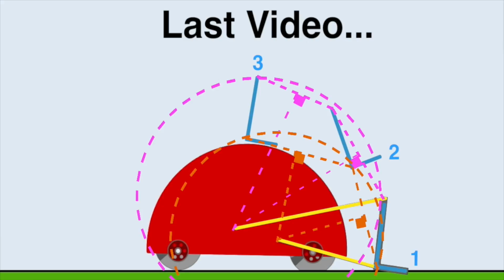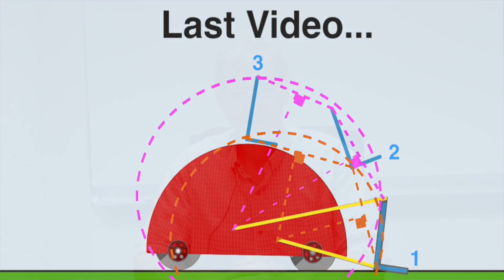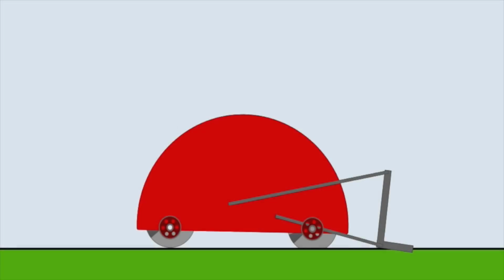And in this video, we're going to apply a technique called the instantaneous centers in order to determine velocities at various points in a robotics application. So, for instance, in this example, the link that we're referring to is ABC, which is the mechanism or the component that actually picks up the balls. That's actually a coupler in this 4-bar, right? The robot itself would be a ground link, so that's the 4th link.